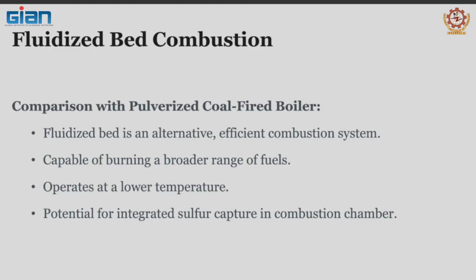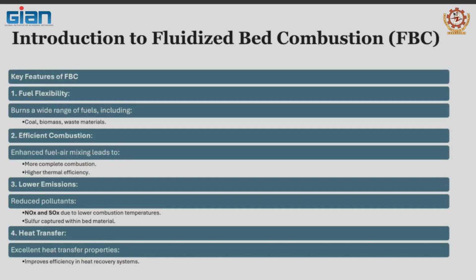In any other system, a pulverized system, sulfur oxides are formed, and unless you have a flue gas desulfurization system above your plant, they are released in the atmosphere. In a fluidized bed, by using sorbents, we prevent sulfur oxides from happening in the first place. So we don't need to clean it because it doesn't form.